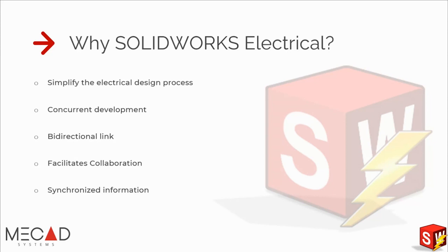So working with ECAD and MCAD together ensures consistency and facilitates the creation of your bill of materials. Some component databases are easily linked to MRP and ERP. If you do have an MRP or ERP system implemented in your company, it works well, and it can also easily be linked to supply info, lead time, and other relevant data captured at the time of design.